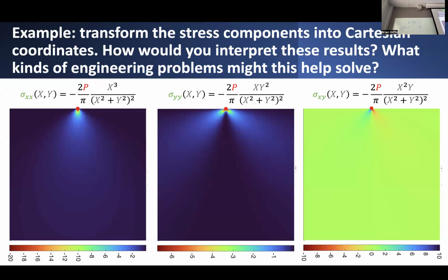Yeah, right underneath the point of application of this load, there's like these concentrated shear forces inside of the member, basically. So you get sort of these localized shear stresses that occur right underneath the point. Now, does that make good sense? I mean, I would argue yes.